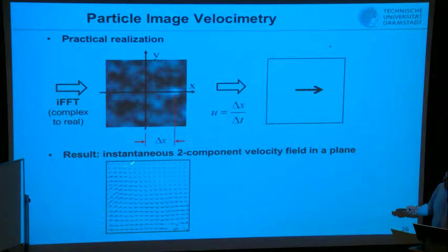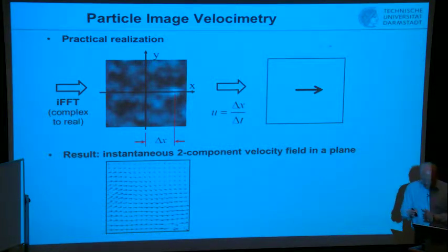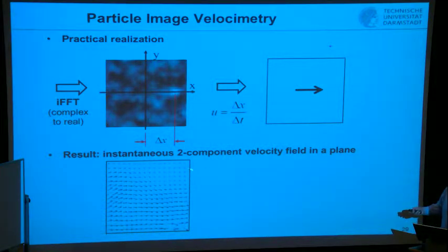And then you get, for this realization, the velocity field, and you typically end up as well with a few spurious vectors. So first of all, the number of these vectors that look strange should not be really large. Obviously, these vectors over here cannot be correct. That is, of course, our knowledge based on continuity and fluid mechanics, that is physically not realizable.